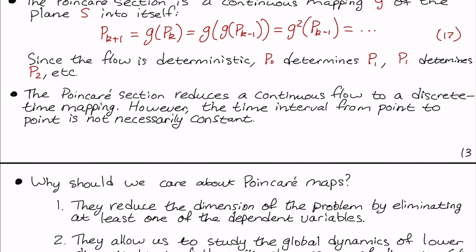Now for real complicated structures, for example, you could consider doing a reduction down or some type of modal expansion and truncation so that you only have two modes and therefore have a resulting four-dimensional phase space. You could then apply Poincare sections to the underlying modes based on that expansion, whether you've done a Galerkin projection or maybe some type of proper orthogonal decomposition, or you've just done a simple modal decomposition and just used assumed mode shapes and incorporated that and included coupling that way.